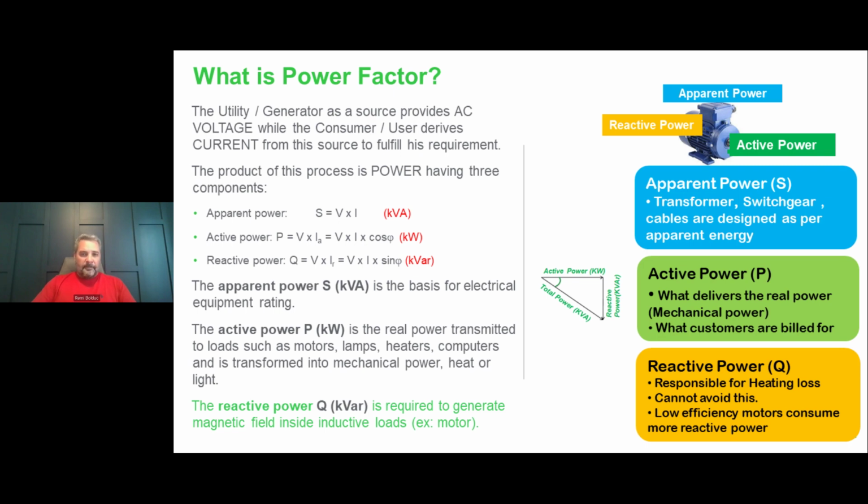all of us know the power triangle, but that's where power factor begins. It's a simple ratio of real power over apparent power. And what creates the displacement between real power and apparent power is reactive power. In most networks, there's a lagging power factor, and it's created by inductive reactive load. The most common one found in our networks is the induction motor. As the shaft turns and drives the load, it generates kilowatts. But in order to do its work, it needs to create a magnetic field internally, and that's what demands reactive power or reactive current. And what needs to be supplied by the power source? Well, it's the apparent power.